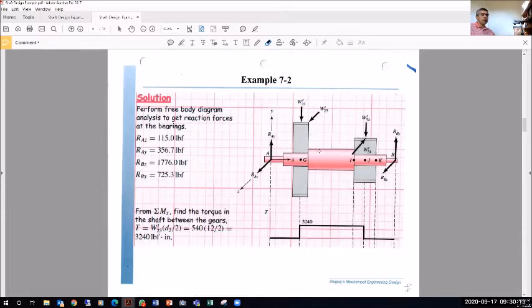So even in the schematic here, I'm showing that with the location of my shoulder, because yes, this point is going to be important because this is where I get the transition. This is where I'm going to need to apply stress concentration factors. So I want to see these details, and I also want to see how the internal forces are going to vary along my section. So I'm looking here at the torque diagram, showing the torque after I calculate it, that the torque extends between G and J.